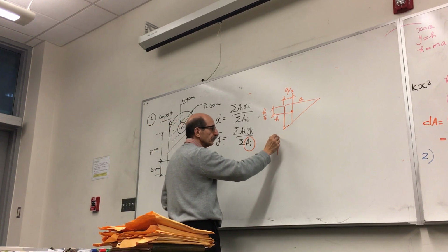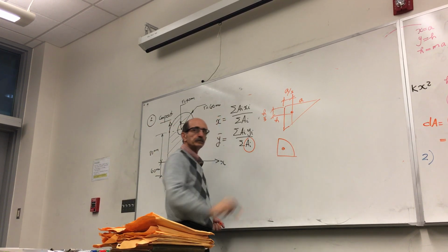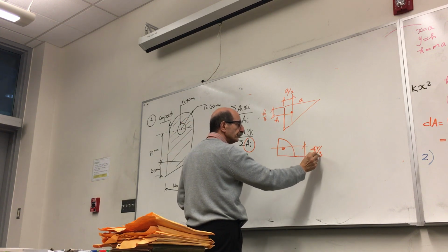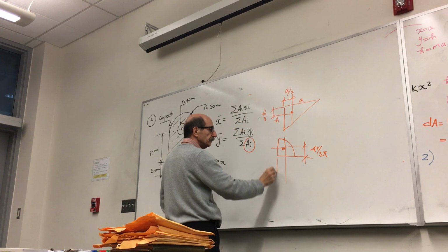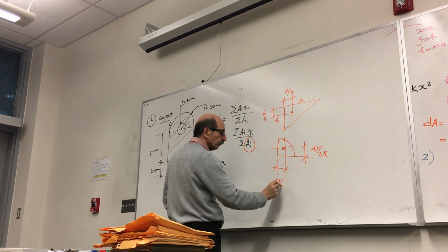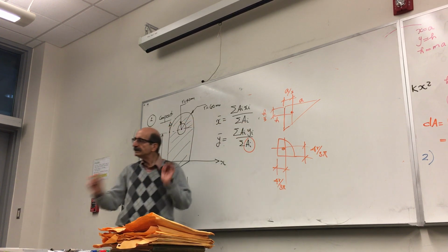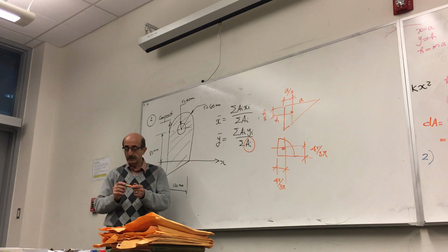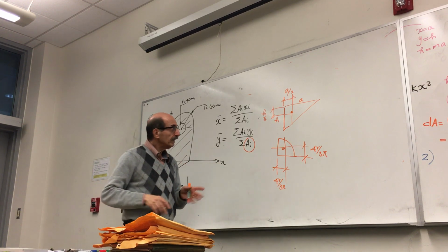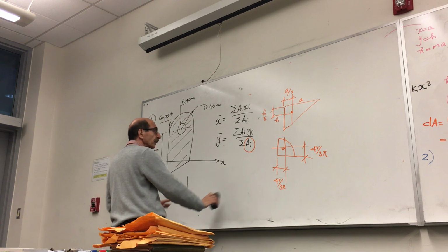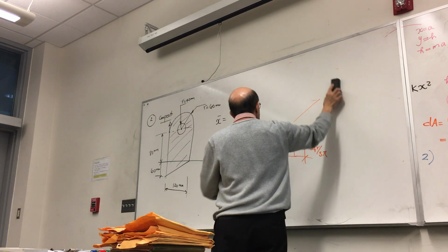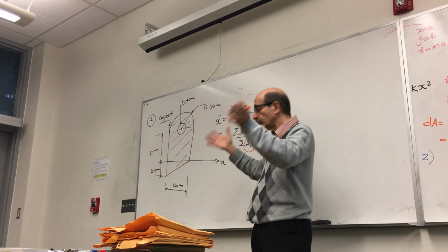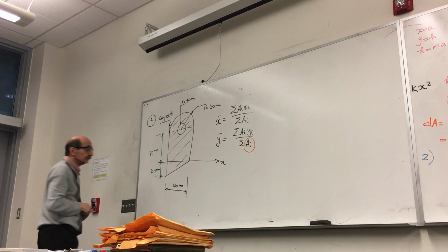For a quarter of a circle, the centroid being here, is 4r over 3 pi from here and 4r over 3 pi from here. All these are tabulated in that table that you have. You don't have to memorize them. You're given that table. So ai's refer to shapes that you create that would be basically one of these shapes, half a circle, whatnot. So that's what we do.